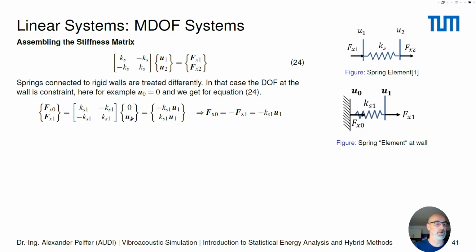this equation of motion for our normal situation, but that means the force occurring here is exactly the opposite of this force on the other side. That's clear. This is a so-called blocked force that guarantees that u0 remains 0, that there is no movement at all. That is a blocked force that always occurs at stiff boundaries.